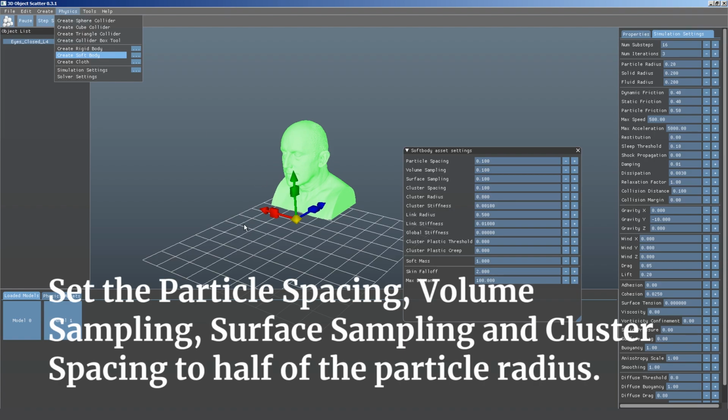So, one technique to fix the collision problems is to lower the particle spacing so more particles can be created in the same asset. Sometimes the penetration issues can occur due to particle gaps in the asset, so if you have a thin layer of particles, the penetration is easier to occur. So that's why we have the particle spacing, so we can have more dense assets. Like this.